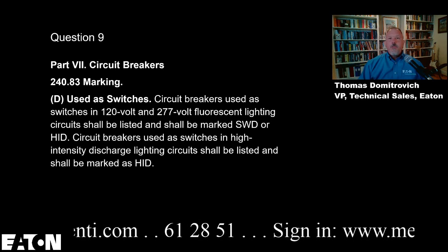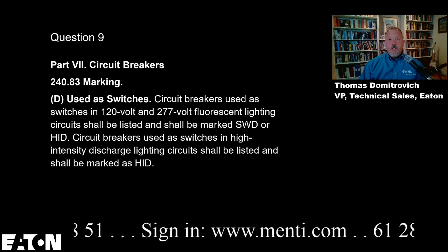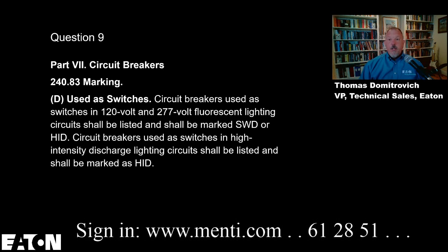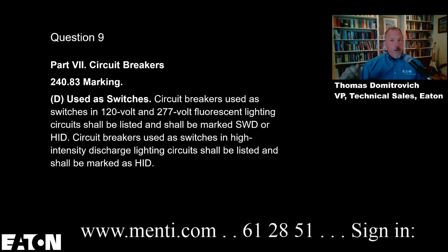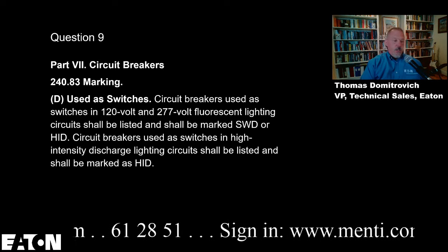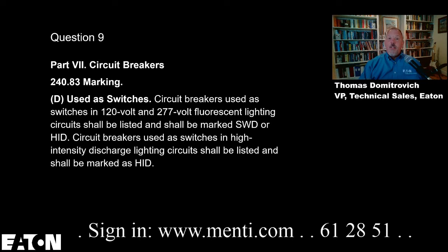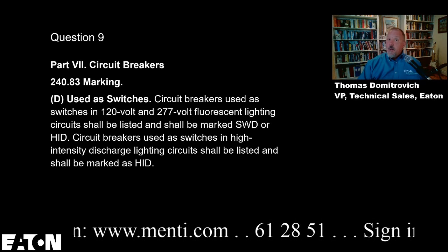From a manufacturing and UL listing perspective, those requirements focus on much more durable switching, because of the cycles and the interruption of the current based upon the phase angles and the power factor of those circuits.